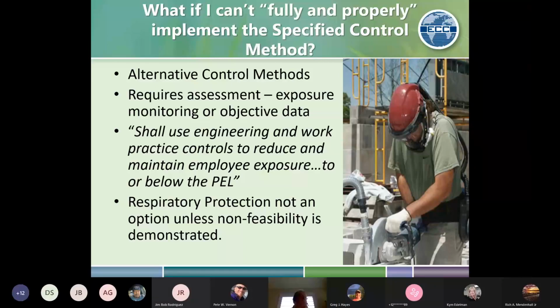If you haven't done this before, and you're going to do respirable dust sampling, it's important that you know the manufacturer's requirements on that particular cyclone, because different people make cyclones for respirable dust sampling, but each one has a specified flow rate.